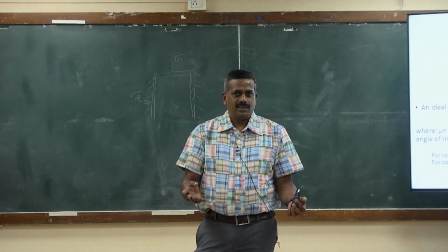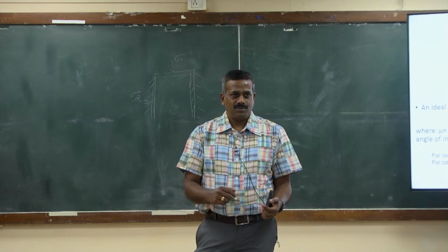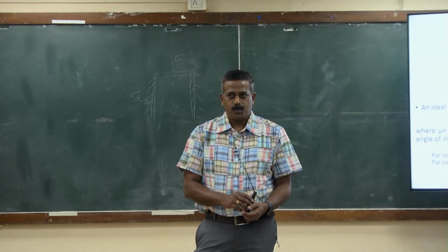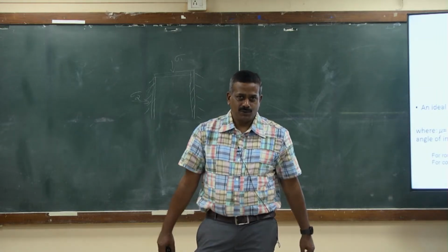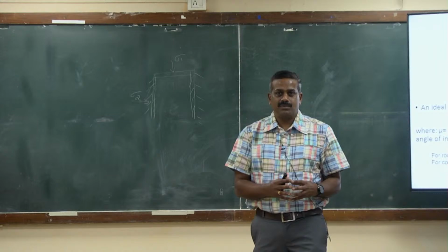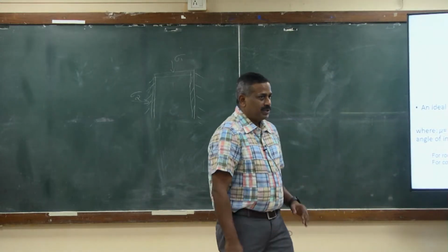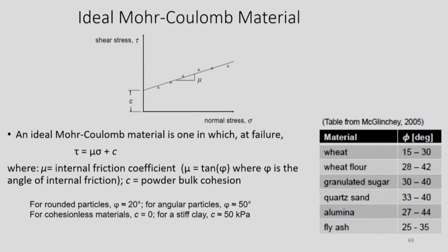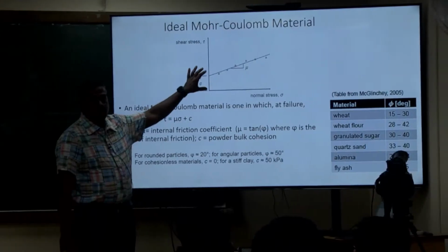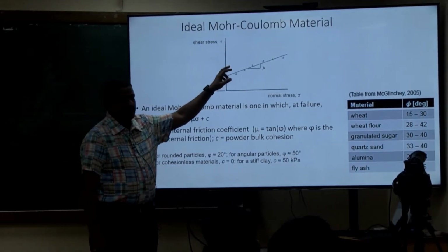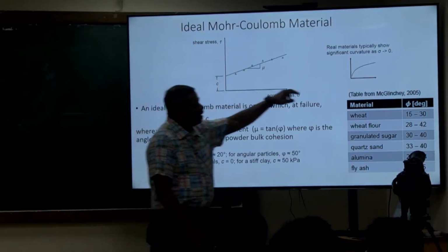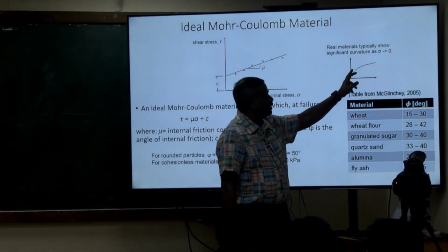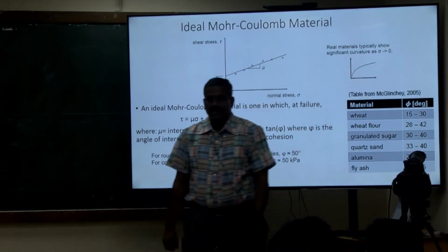Why do regular powders not follow the Mohr Coulomb law? It's not attraction, it's due to the presence of inbuilt cohesion between the powders. You take any biological material, grains or powders, there will be some inbuilt cohesion. So you might not get a linear relationship, as in the curve here for one example material. Usually you see a curvilinear relationship.